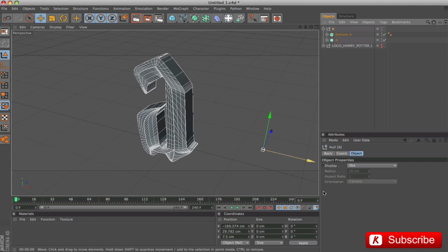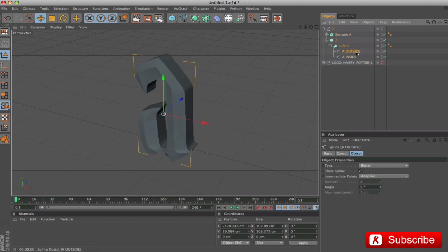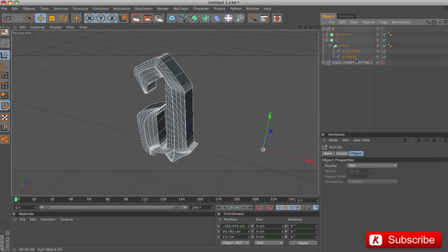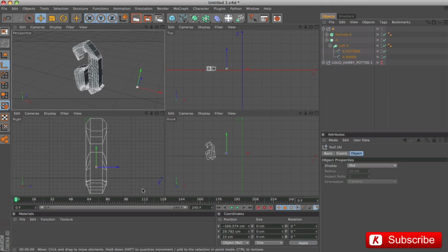Every time we create a group, the center axis is decentralized. We must then center it with the x and y coordinates of the track outside. Activate the pivot tool, copy and paste the coordinates, and we put on Z the value 15.